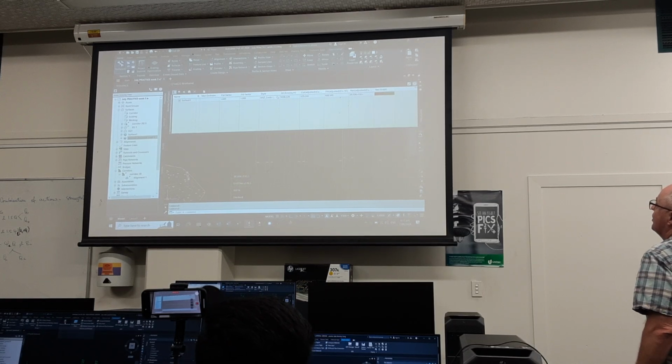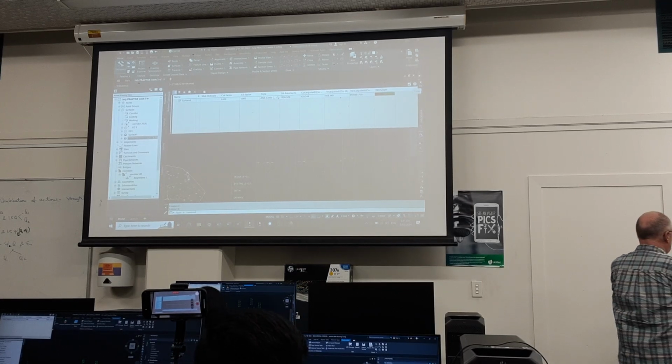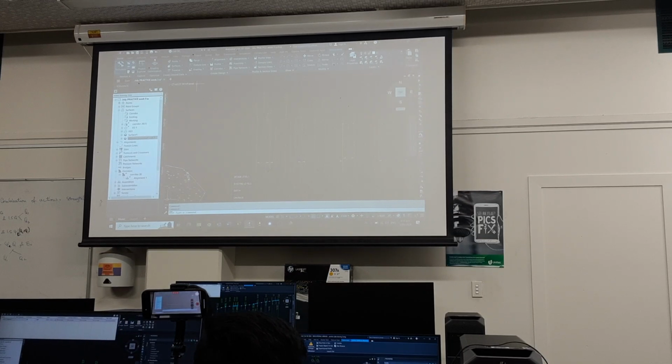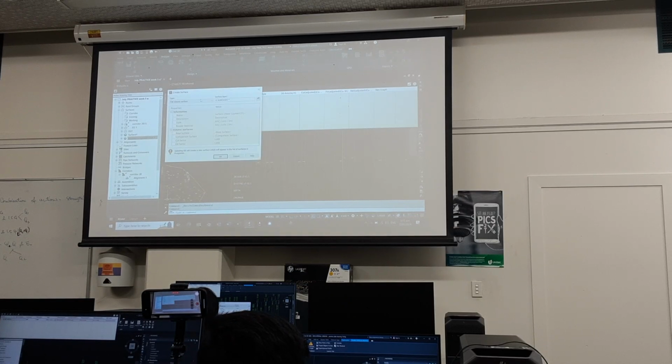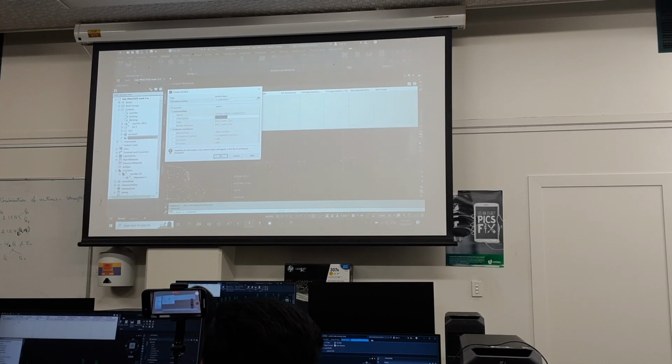I'll just do that one more time because some of you might have missed the steps there. I'll delete this, remove this surface and remove that box. So we need to go to Analyze, Volumes Dashboard. We go to the little cake with the sun above it, cherry on top. Click on that. We need to give it a name, number 3. Cut this time, because my red is bigger, and the cut is bigger. Road surface, red, 3.